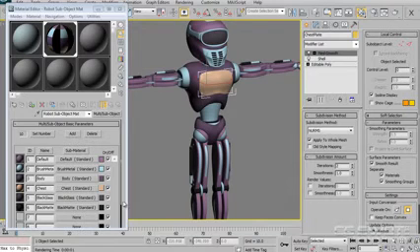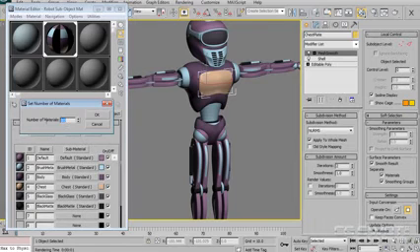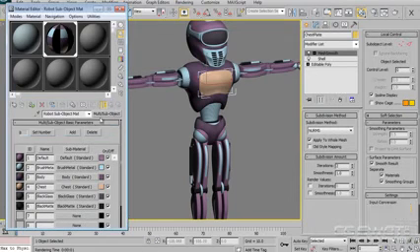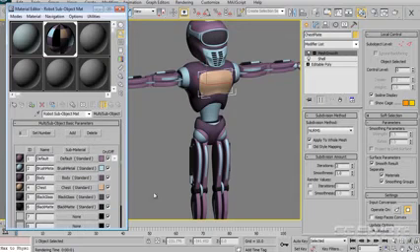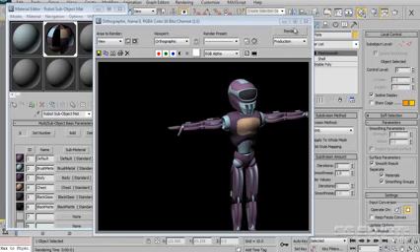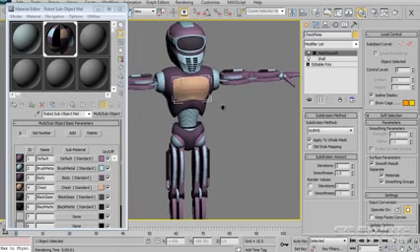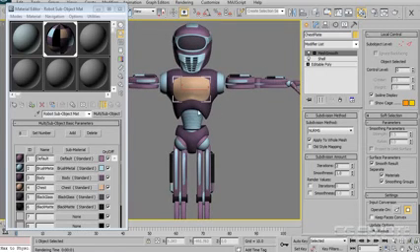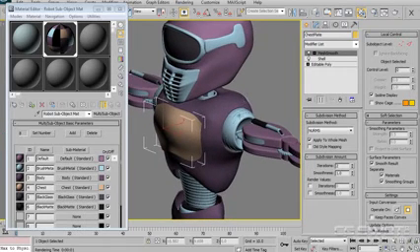So what I'm going to do is actually leave it at 8, and by default it's 10, so I can just go in and set the number, and we'll make it 8. The reason why I've left it at 8 is it gives me a bit of wiggle room, and I can actually add some other, more unique materials later on. And if we give it a quick render, you can see that we've literally got our model broken up, and that's the first step. And now what you do is just simply go ahead and start to specifically design your materials based on those sub-selections.